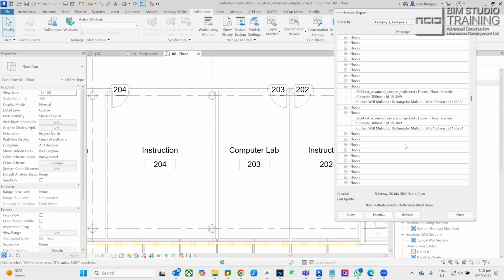So what is the value? Now, no one will use Revit to do this because you cannot save this. So you do this and then go for lunch and then you don't know where you're up to. So people use Navisworks. Okay, but clash there is nothing big. It's simple. The thing is, everybody can do this clash detection without understanding whether you've got a solution or whether it's important or not. They do not have priority. That is a problem. So clash detection is no big deal. Just press a button. All right.